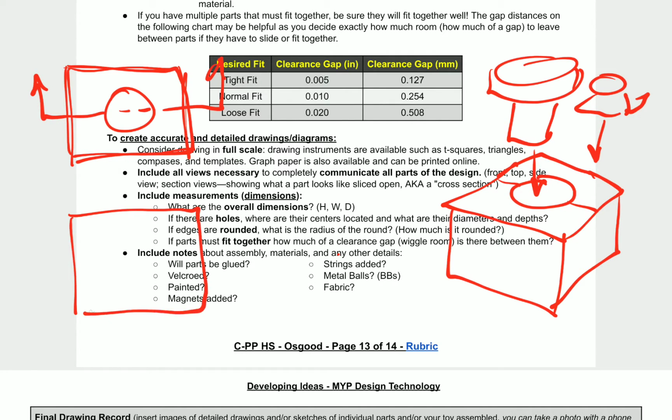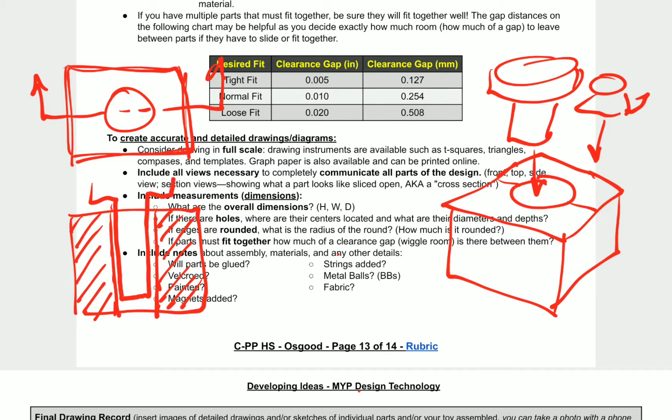And now we might see, instead of just seeing this plane like this, or maybe even seeing the sides of the hole with dashed lines, we could see as if this were sliced open here, okay? And now we can even start to draw in and say, okay, there is the bolt, right? That's the bolt that we want to have there. And this is what it looks like on the inside. Let me just fill that back in because I erased it.